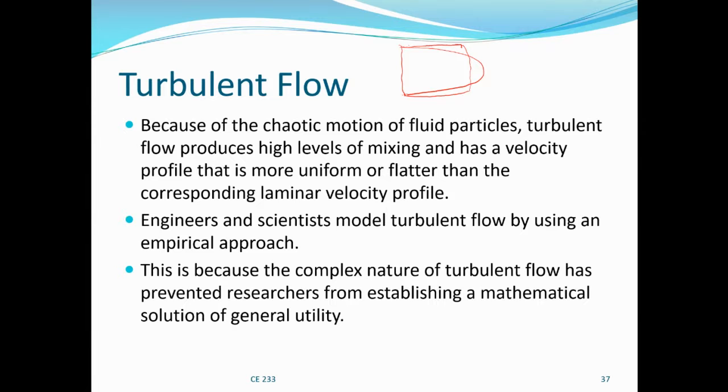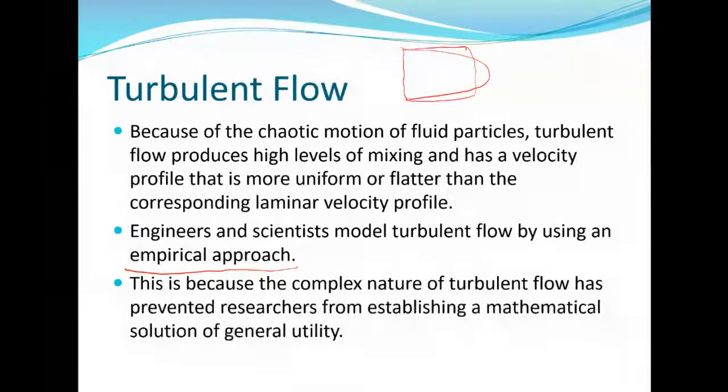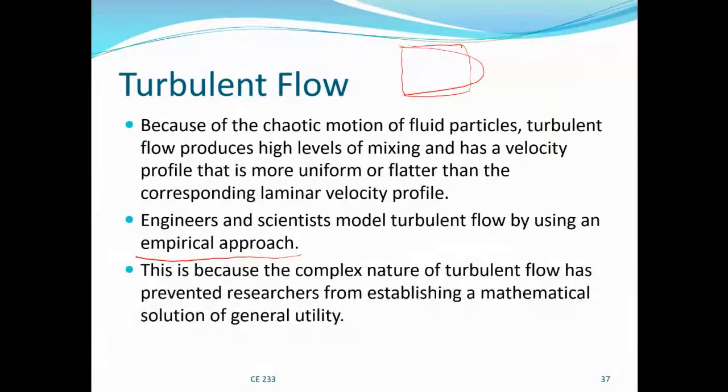Engineers and scientists model turbulent flow by using an empirical approach. What's an empirical approach? It is different from analytical. For laminar flow, we derive the stress distribution and the head loss formula using analytical considerations. By analytical consideration, we look at the force balance, the application of Newton's second law of motion, and then simplify the equations and arrive at the relevant equation.